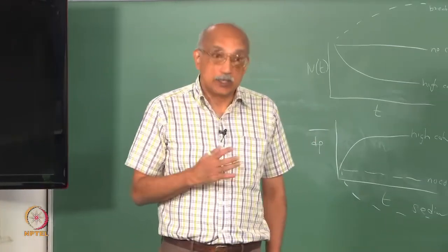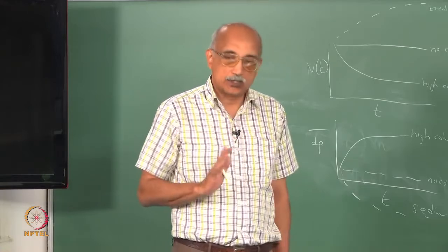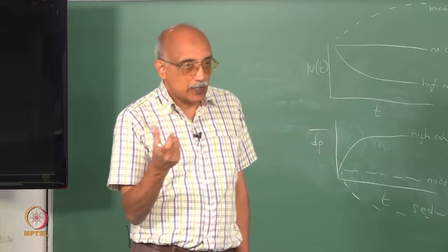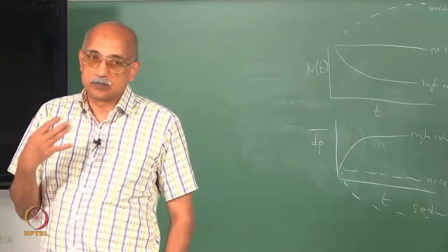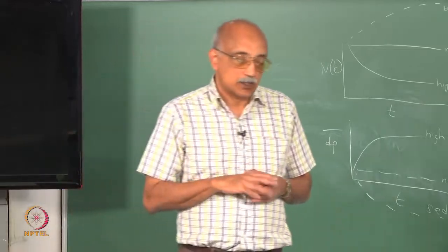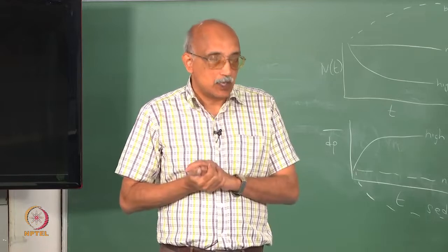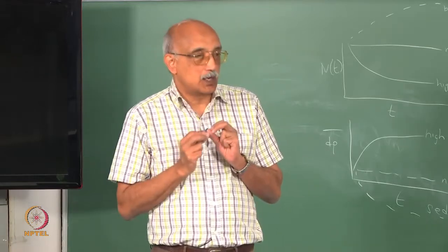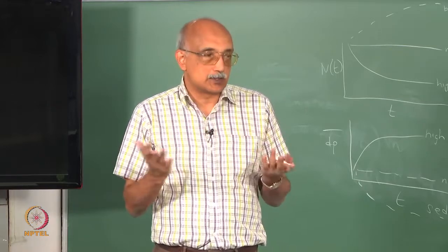But in general, cohesion is going to happen, and initially the cohesion will be pairwise, and then they will start adding more and more particles to the matrix, and you will start getting these clumps of particles, which is, as I said, not to be desired in most cases. However, there are certain industries, certain applications where you do want good cohesion. An example is the pharma industry.